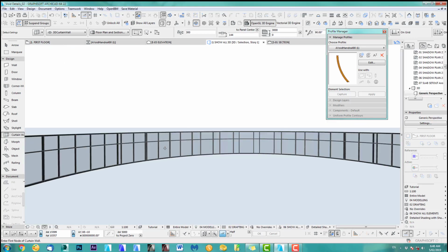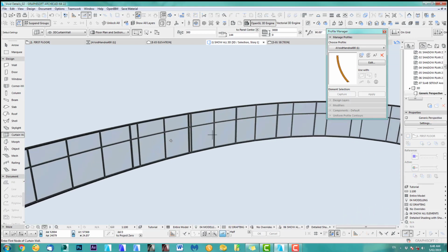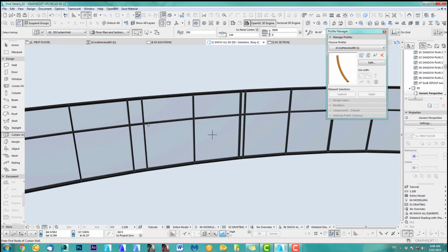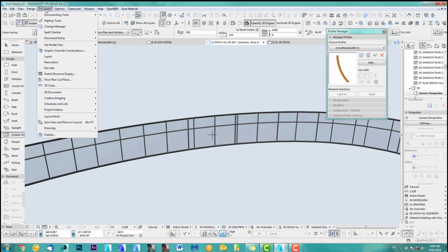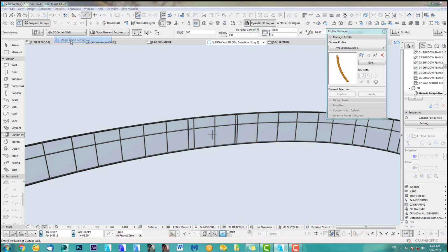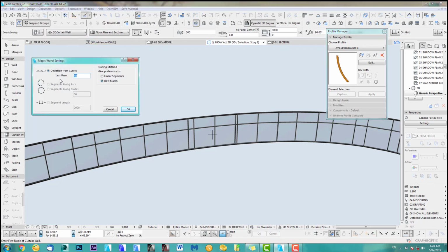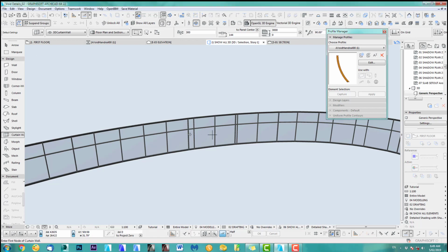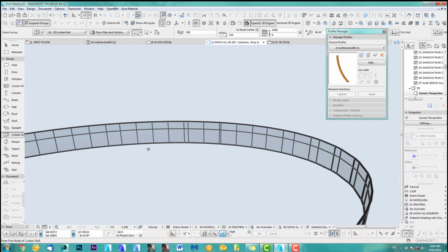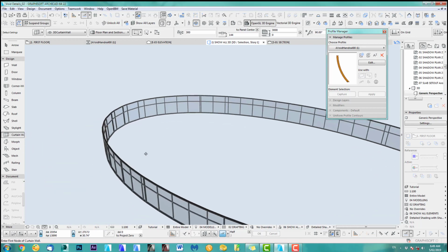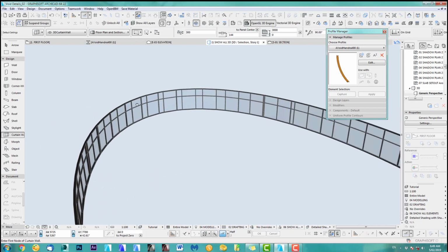There you go, see? It can't handle an ellipse very nicely because I show you, you told it to go less than 40 and you told it best match. So ARCHICAD just works this out and every so often it puts in like a polygon for the curtain wall tool. And you can just see yourself, it's not gonna work.